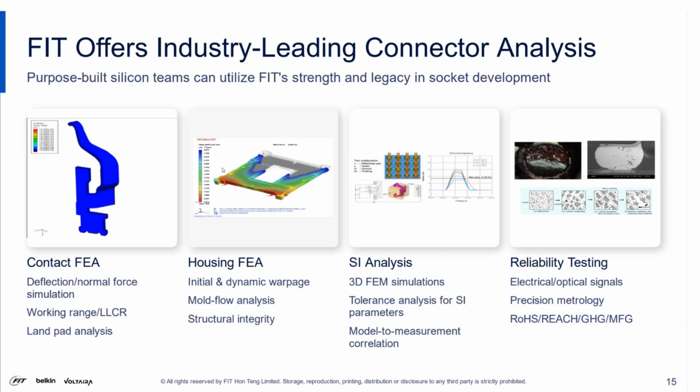We have multiple teams with high degrees to run our contact mechanical FEA analyses. We also have an advanced molding department team, which gives us predictions and improvements when it comes to warpage, both initial and dynamic warpage. Dynamic warpage is the change in the shape of the socket when it goes to reflow temperatures, and also structural integrity of the housing.